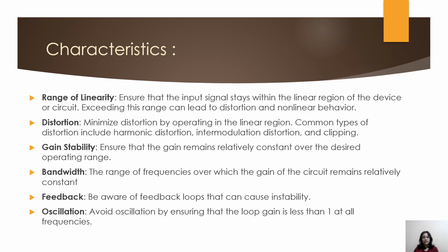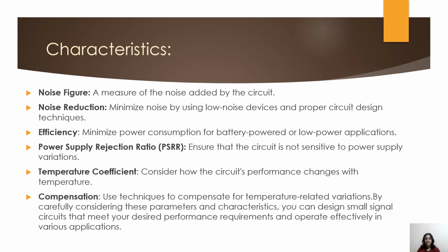Feedback. Be aware of feedback loops that can cause instability. Oscillations. Avoid oscillations by ensuring that the loop gain is less than 1 at all frequencies. Noise figure, a measure of the noise added by the circuit. Noise reduction, minimize noise by using low noise devices and proper circuit design techniques. Efficiency, minimize power consumption for battery powered or low power applications. Power supply rejection ratio PSRR, ensure that the circuit is not sensitive to power supply variations. Temperature coefficient, consider how the circuit's performance changes with temperature.